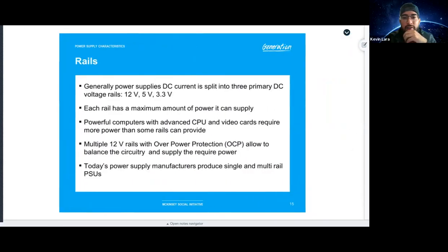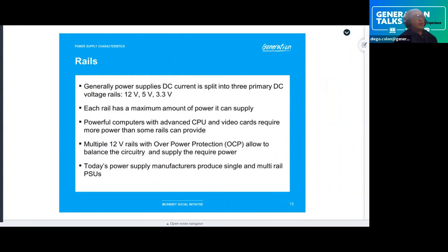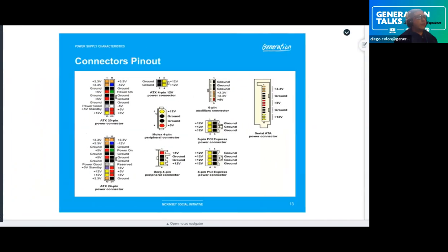Those colors never change or get updated or anything, right? That is correct. Those are the colors. The red is the red, the yellow is the yellow, and the orange is the orange. As for the purple, we learned that one's a cute one. It's 5 volts standby. And the other one that's also very easy to spot is the blue one, which is a negative 12 volts. It's the only odd ones in there, besides obviously the gray. Questions? Doubts?